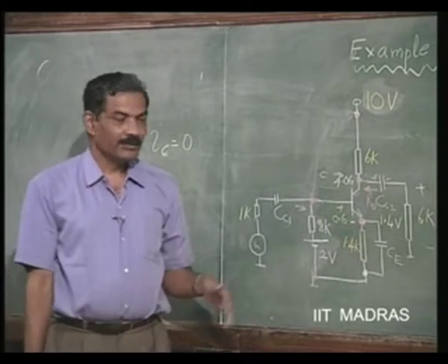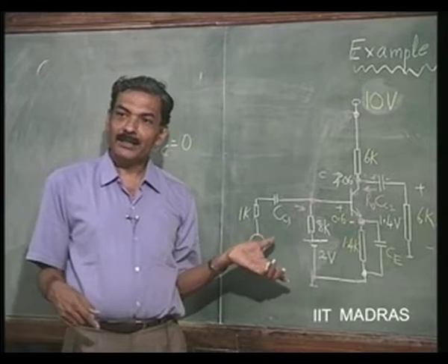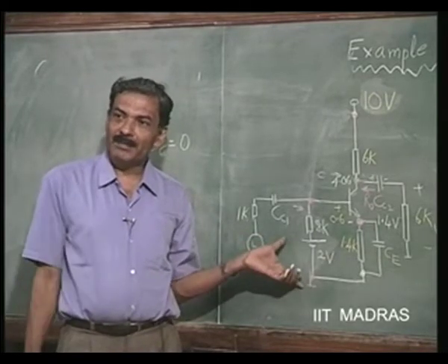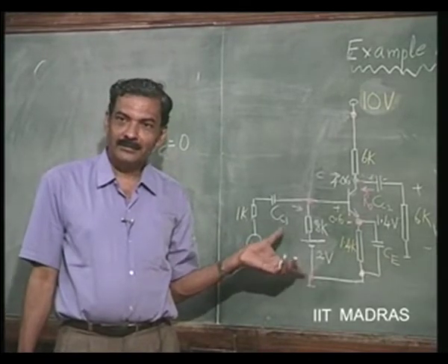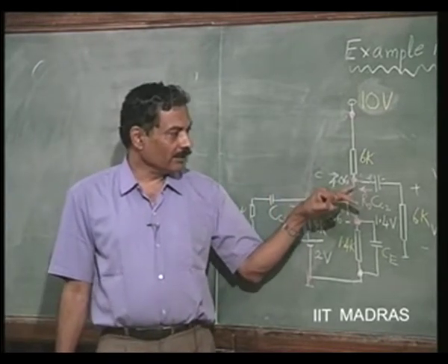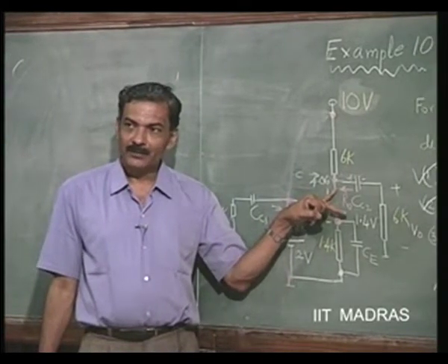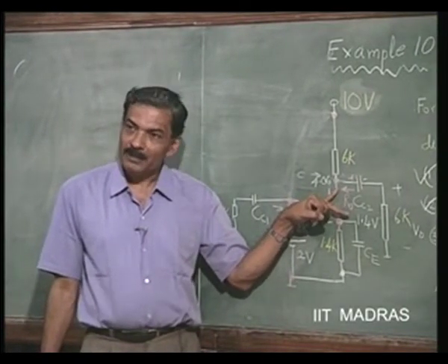So that 1 milliampere change may have been brought about by a disproportionate change here because of the nonlinearity. Now that is of no consequence. So this swing here, current swing, for it to go to cutoff is 1 milliampere.